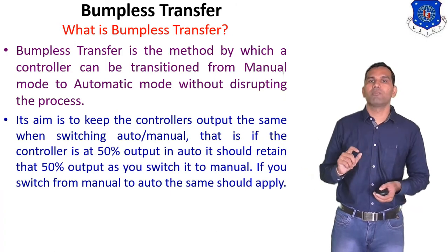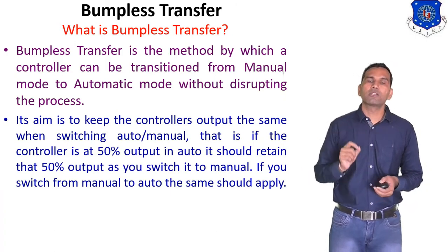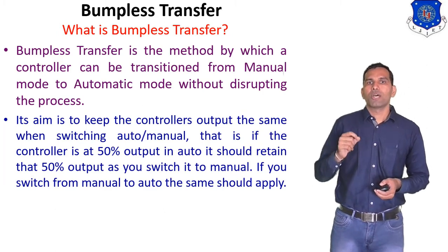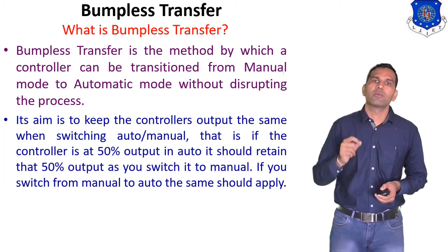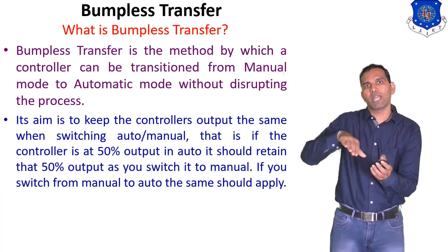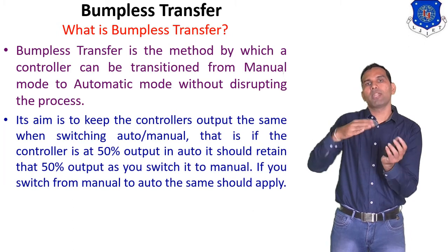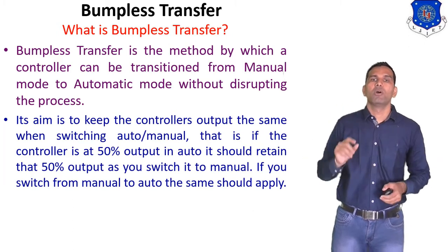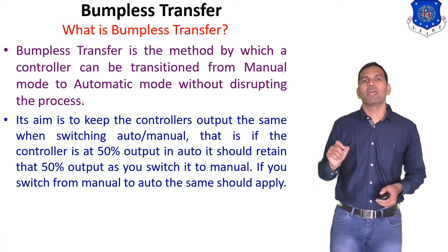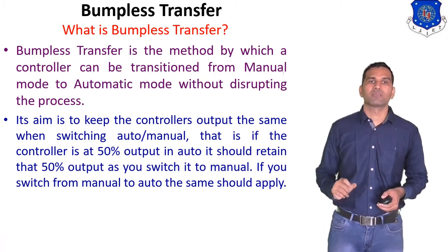Bumpless transfer is the method by which a controller can be transited from manual mode to automatic mode. That means we can transfer the controller from manual mode to automatic mode without disturbing the process. So it's known as bumpless transfer.